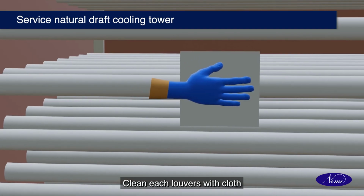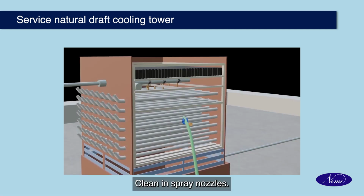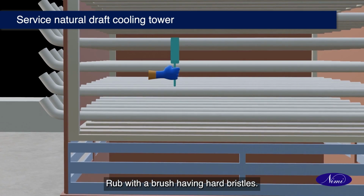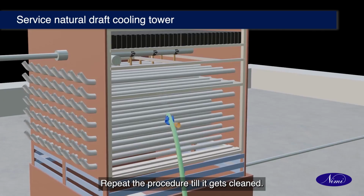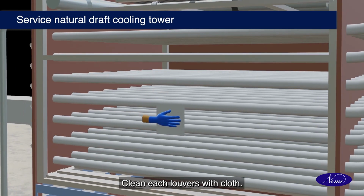Clean each louver with cloth. Clean the spray nozzles. Clean the louvers. Spray forced water on each louver. Rub with a brush having hard bristles. Again spray with forced water. Repeat the procedure till it gets cleaned. Clean each louver with cloth.